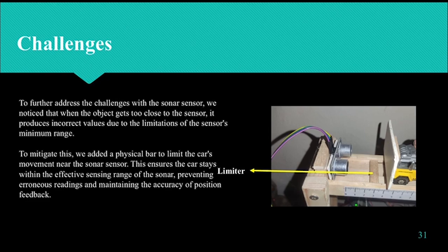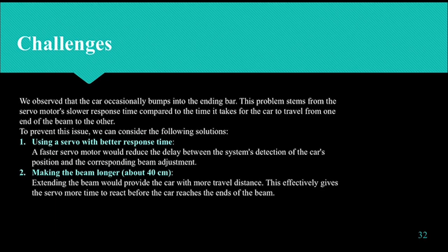Another challenge was that the servo response time was slow. That's why the car here was hitting the sensor, and the sonar sensor threshold distance is from 2 centimeters to 200 centimeters. If the object gets too close to the sensor, it can't measure the distance. That's why we used an obstacle to maintain the minimum threshold distance for the sensor.